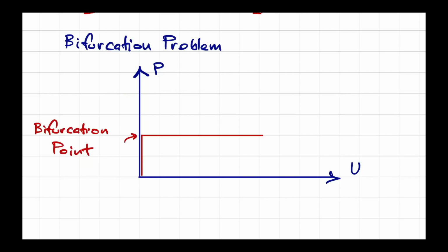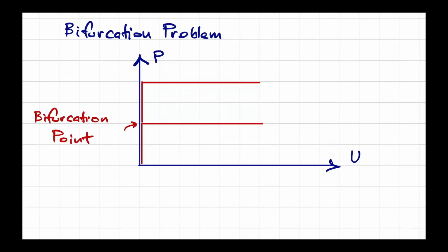If it does, then it's going to go to the next bifurcation point. So that's another route. Another eigenvalue. Okay, because you don't have just one. But the thing is that your structure will buckle at the first buckling load. So you will not see the second bifurcation point, but it exists mathematically. Okay.